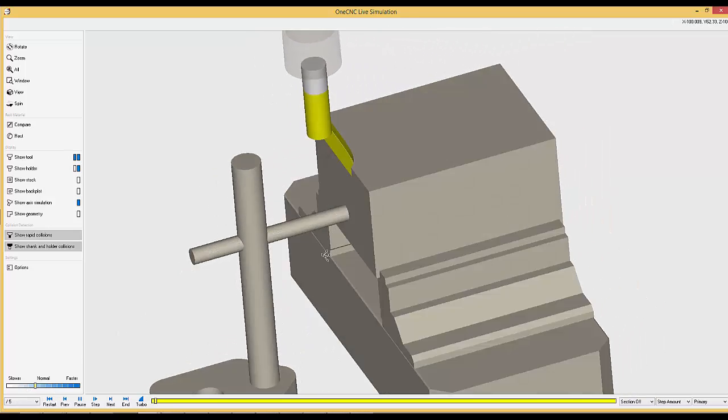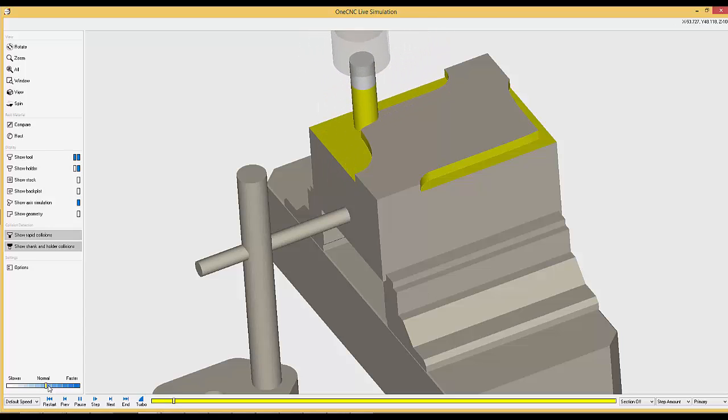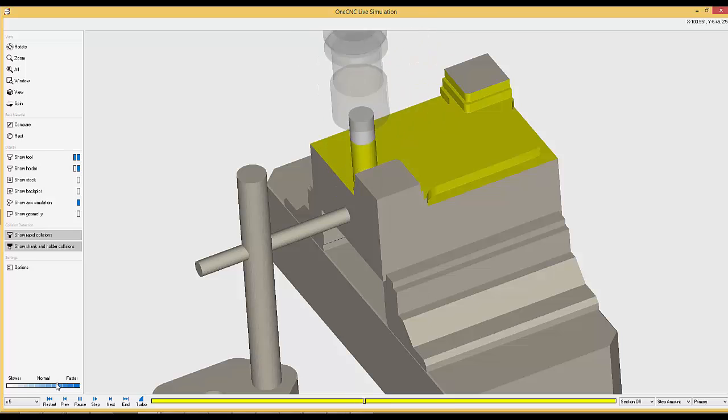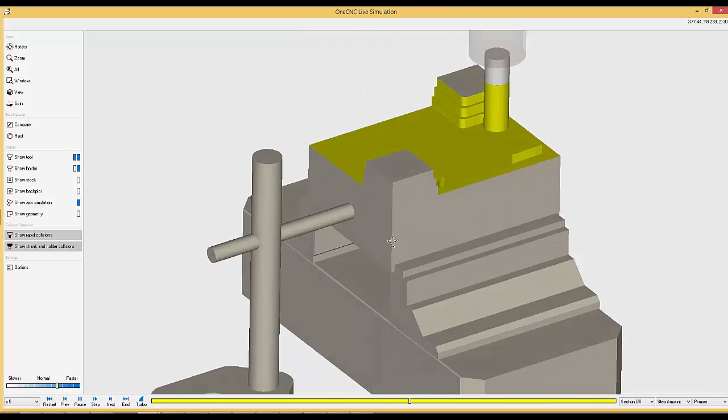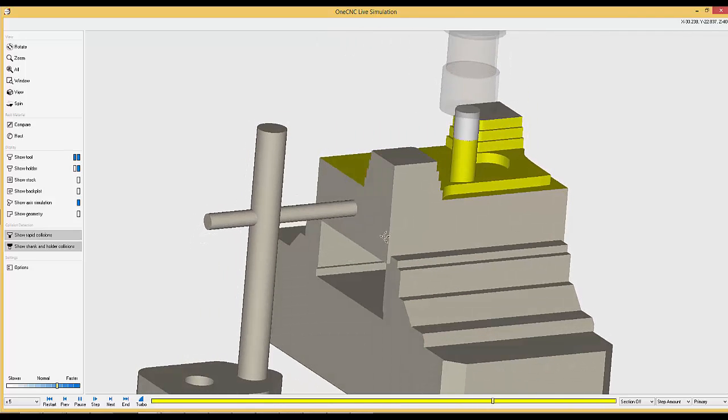And straight away you can see the tool is plunging into fresh air. It's then radially moving in towards the profile. You'll know there are no fresh air cuts anywhere. Mill Professional knows the size of the boundary is the same size as the billet, so there will be no fresh air cutting around the part. And we'll just accelerate this simulation through. As I said, you're fully collision checking your entire setup of the machine in Professional.